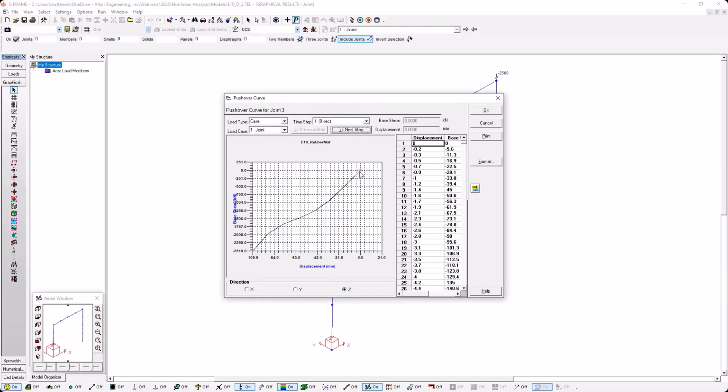It's subtle, but we can see differences in the deformation curve as we increase the base shear and unload it again. We're just applying this base shear in one single direction, but as we described earlier, it can also be enacted in a similar way if we were to pull this up rather than push it down. So we're only seeing half of this curve essentially.